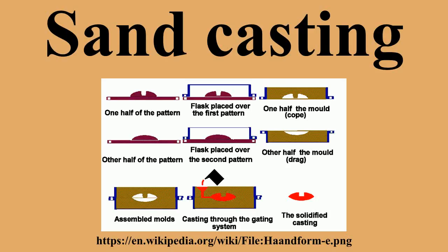A special vacuum-forming flask is placed over the plastic pattern and is filled with a free-flowing sand. The sand is vibrated to compact it, and a sprue and pouring cup are formed in the cope. Another sheet of plastic is placed over the top of the sand in the flask and a vacuum is drawn through the special flask. This hardens and strengthens the unbonded sand.